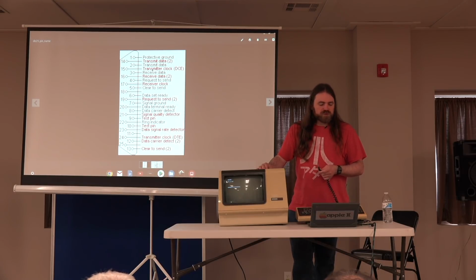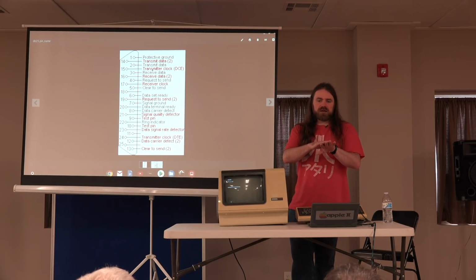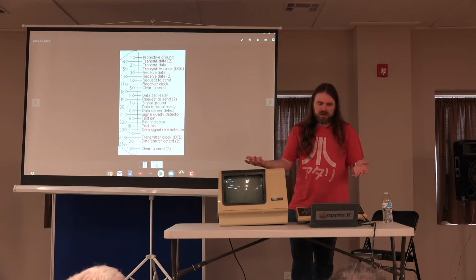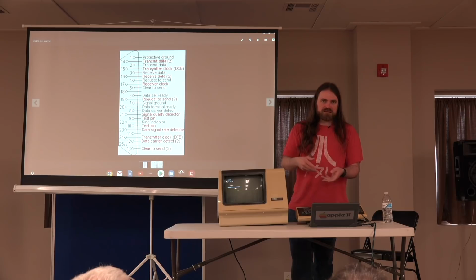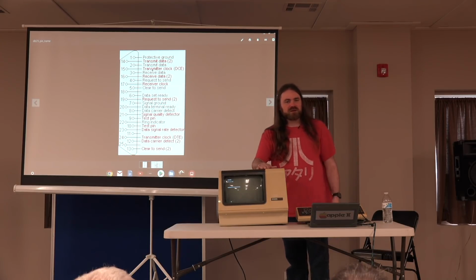If you ever have a choice between an LK201 and an LK401, get the 401. The LK201 keyboards are heat staked together and the membranes fail. So when one breaks, there's really not a good way to fix it short of breaking all those heat stakes, taking the whole thing apart, fixing the membrane, and sticking it back together with, I don't know, screws or something. It'd be a nightmare. The 401, however, is held together with plastic snaps. You can take the whole keyboard apart and clean it. Even if somebody spilled a Coke in it 20 years ago, you can fix it.